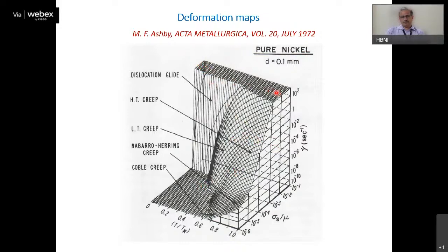And this region basically corresponds to the dislocation glide. So you can see the dislocation glide is important at very low strain rates also and at lower temperature. So mostly the quasi-static experiments on plastic deformation, these will be the dominant player in the plastic deformation. And further in future lectures, when I will talk about the plastic strain-induced phase transitions, basically we will try to explain the phase transition